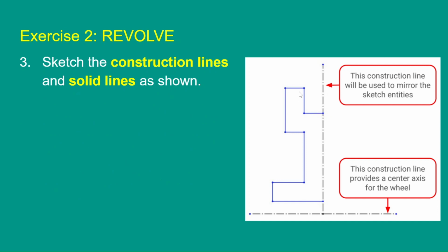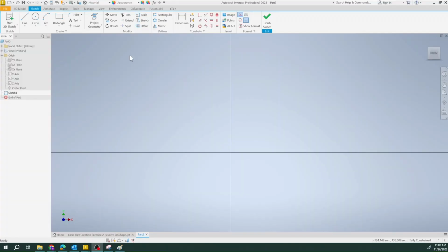So then I go back over and I check, and it says that I'm going to need to make this particular sketch. Looks like I have to make these blue lines. Those are my object lines. And then I have to make these as my center lines. So I'm going to go and create those, and I'm going to make sure that this right here winds up on my center point when I make this. So I'm going to create a line, and this line is going to go along my x-axis, and I want it to be a construction line, so I want to make sure that this is toggled on right here.